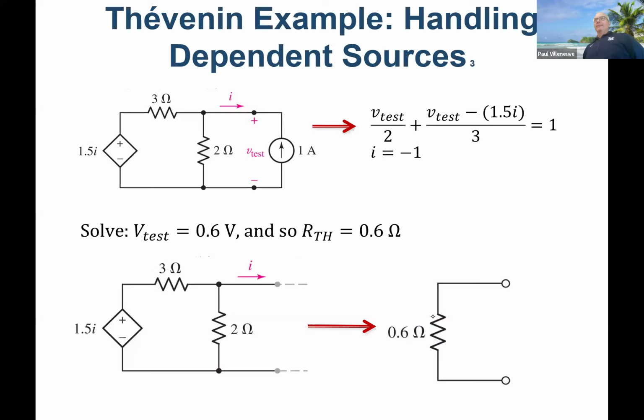So I'm giving you another tool. And in some cases, it's actually easy to do that. Like if you have a physical circuit that you've built and you want to find the Thevenin equivalent, why not go ahead and put a 1 volt or 1 amp test source instead of doing the calculations and physically measure what it is.